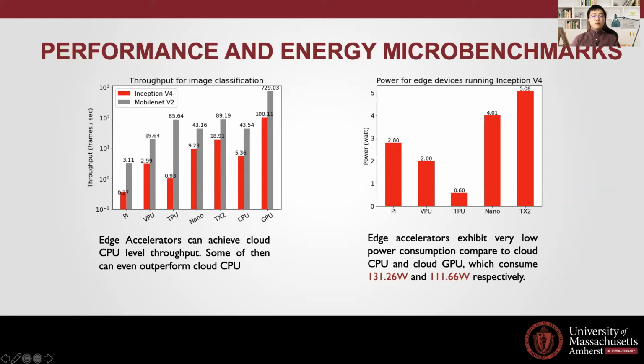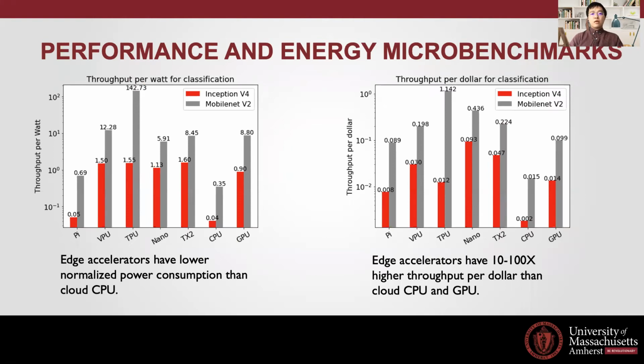right figure. The edge TPU achieved the lowest power consumption when running Inception v4, and the power consumptions of cloud CPU and cloud GPU are 131 watt and 111 watt respectively, which are 2 orders of magnitude higher than that of edge accelerators. Next, we normalize our measurement.